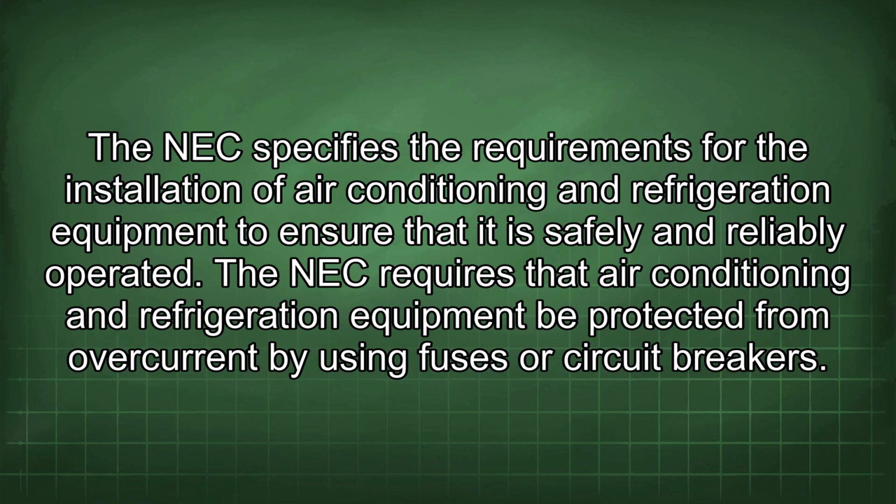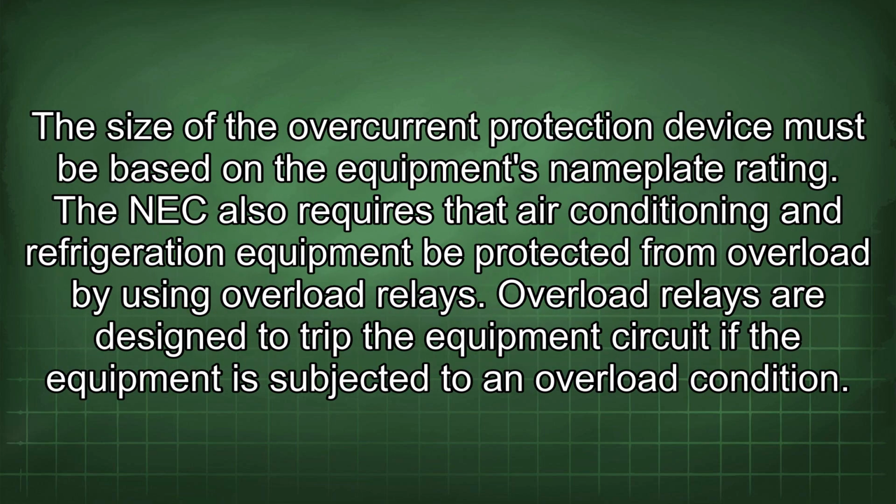The NEC requires that air conditioning and refrigeration equipment be protected from overcurrent by using fuses or circuit breakers. The size of the overcurrent protection device must be based on the equipment's nameplate rating. The NEC also requires that air conditioning and refrigeration equipment be protected from overload by using overload relays. Overload relays are designed to trip the equipment circuit if the equipment is subjected to an overload condition.